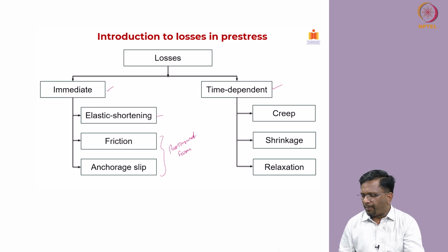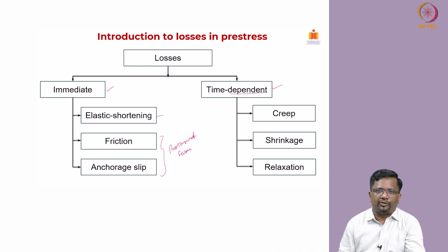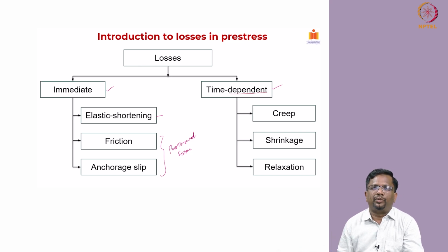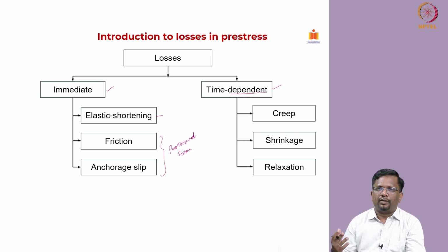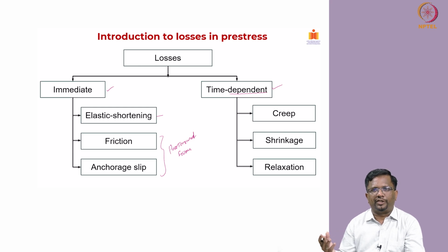Now, with respect to time dependent losses, as the name says, it is a function of time. Depending upon at what time you are doing the calculation, the effect of these phenomena changes. Concrete creeps over a period of time, and depending upon what time you are looking at, the amount of creep will change, right.